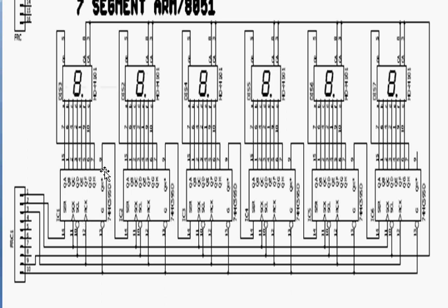As addressed, if you want to transfer data from one shift register to another shift register, pin number 9 is connected to DS of the second shift register. So one bit at a time from this register gets transferred to this unit, and similarly you have to follow that for the remaining shift registers, so that all information from segments 1 to 6 will be displayed on those 7-segment modules.